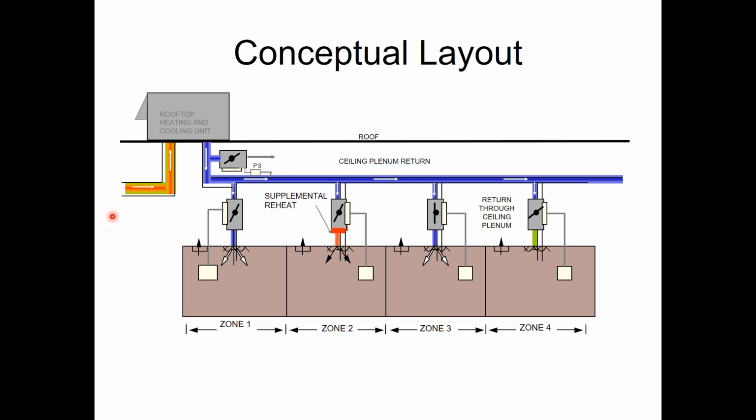Chun asked, out of curiosity, why is the supply air 55 degrees? Why no higher or lower than 55? It can be higher or lower, and if you do that, you just need to design the system for that. For example, there's a library in Naperville on 95th Street where the entire VAV system was designed for either 45 or 47 degrees of cooling, which meant the chiller, instead of providing 45-degree water, has to provide like 39-degree water. The reason they did that was so they can make all the ducts smaller.